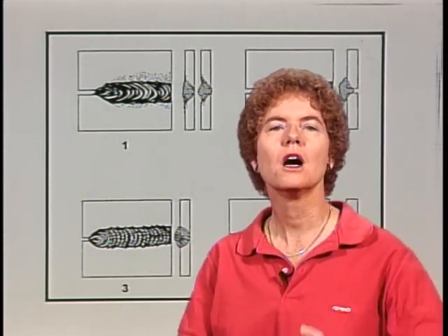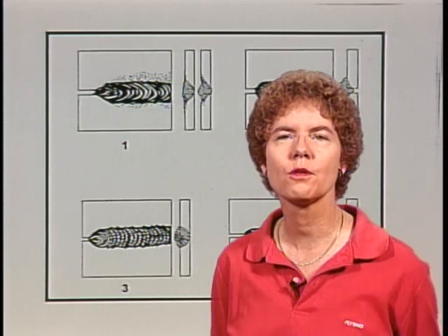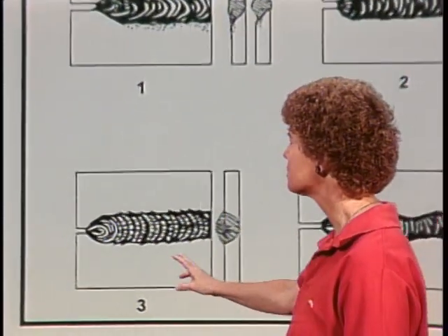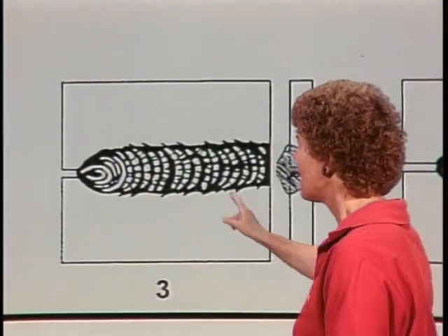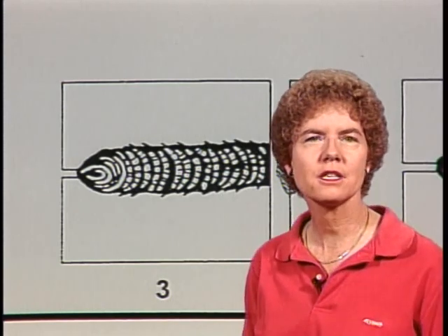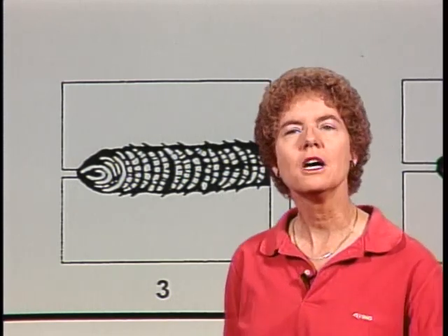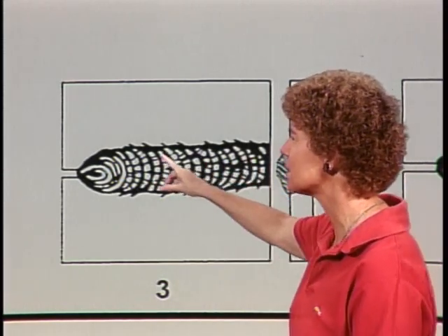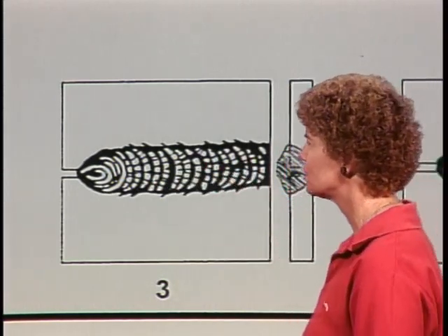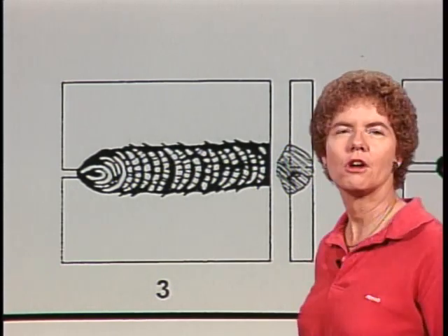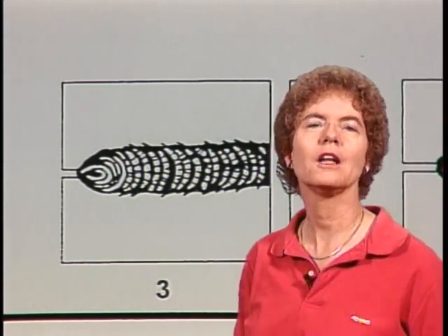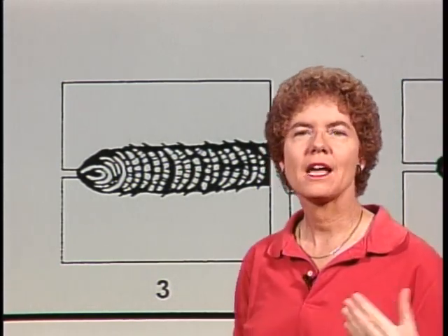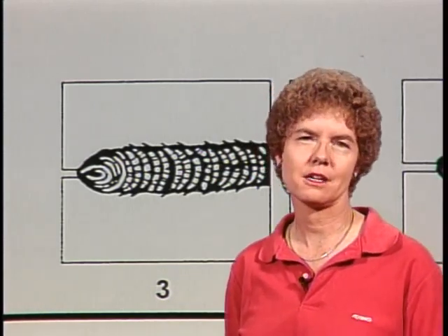The FAA may ask you, for instance, which of these welds would be caused by an excessive amount of acetylene. Take a look in the lower left-hand corner at illustration number 3. That weld would be caused by an excessive amount of acetylene because what you've got here is slight bumps along the center and craters at the finish of the weld. Those are caused by the boiling of the puddle, and that's caused by excessive acetylene being used.